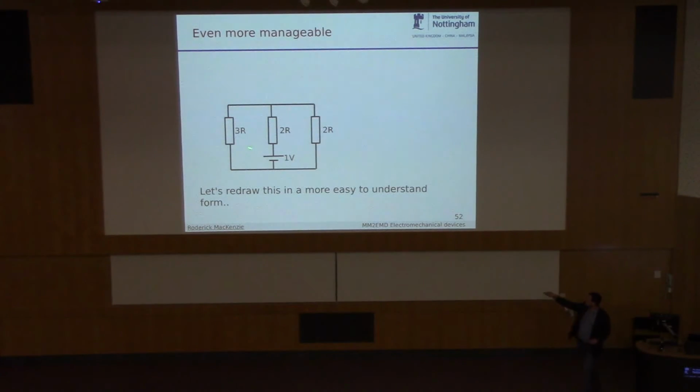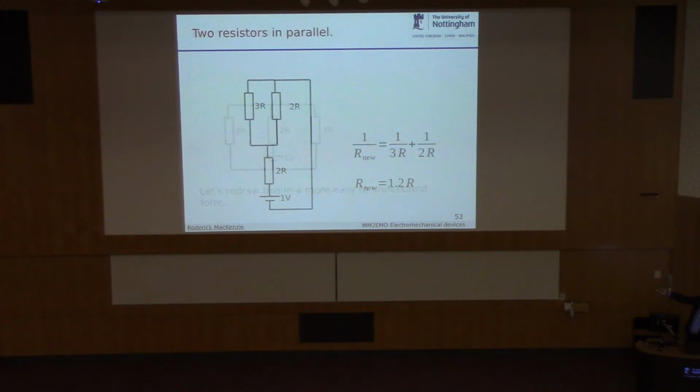So can you see, we've got 1 volt here, and it goes to 2R, and then the current goes either through here or through here. So these resistors here are actually in parallel. Now, it's a bit awkward to analyze like that, so I can flip these resistors up, and we can draw the circuit as a linear circuit. You work through this on your own, you'll see what I'm doing. I've basically moved this one and this one up to the top. And this is starting to become a much simpler circuit to analyze.